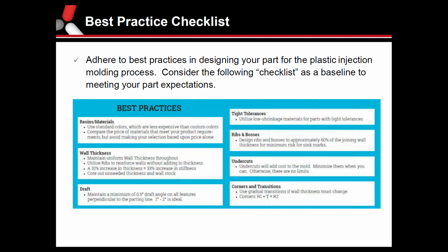Resins and materials, you try to stick to standard colors or standard off-the-shelf materials. Try not to get anything exotic or out there. It just leads to it can be costly and run into lead time issues, especially at low volumes.